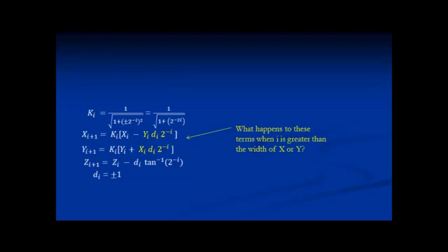Before proceeding to how to get rid of the k sub I term in the iterative process, let's look at an interesting fact about the 2 to the minus I term and our x and y values. In hardware, the x and y values will be a certain fixed number of bits wide. Let's say they're 16 bits wide. What happens to the x sub I plus 1 and y sub I plus 1 calculations after the 16th iteration?